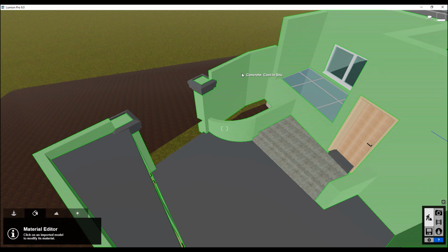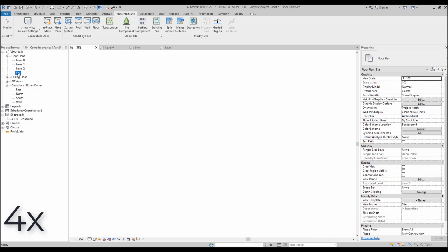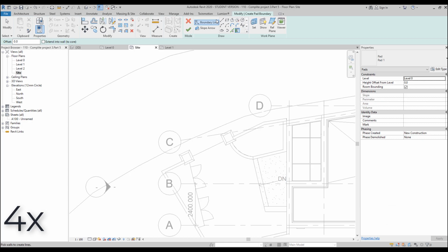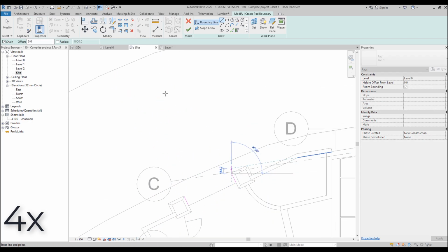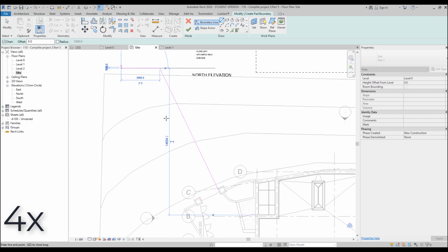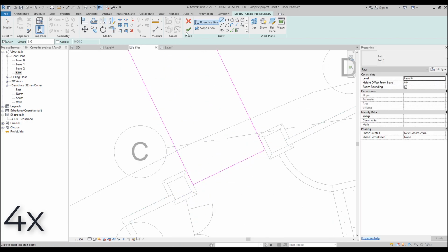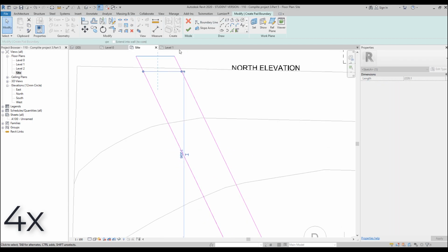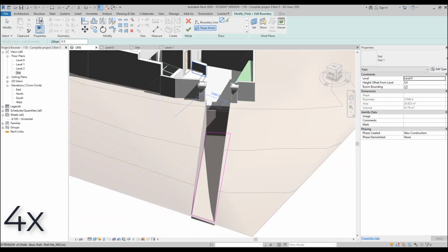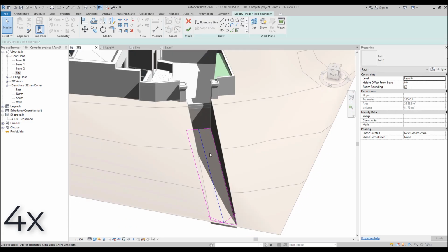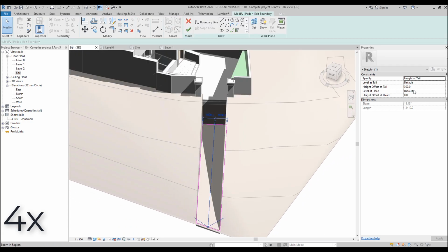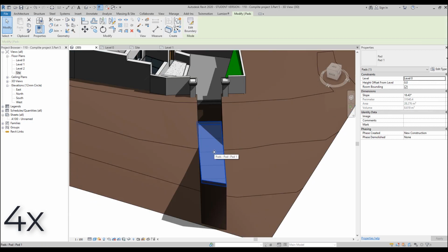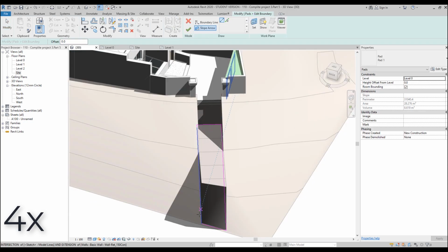Now we should go back to Revit, and we will continue working with the pad, because we also have the right side of our pads. Let's go to the side view again, and I will use the pad tool again, and now I will do the road with the sloping. Just draw your road where you want to direct it, and don't forget one thing: it cannot go outside your topography. After that, just draw the line which shows the direction of the sloping, and change the direction.